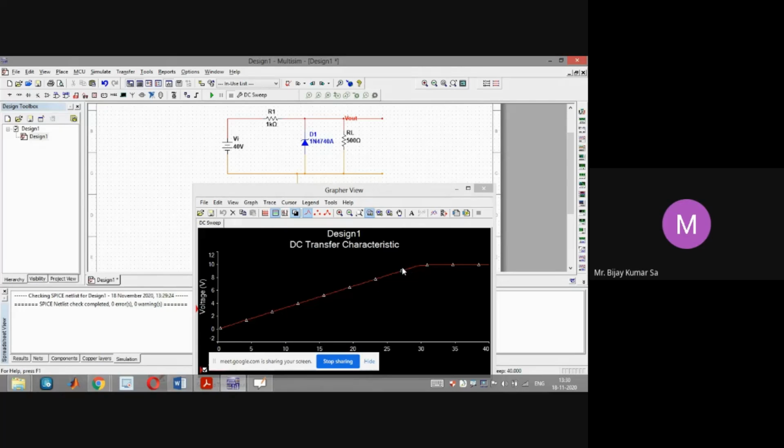Because V output is directly proportional to Vi in that case. From Vi equals 0 to 30 volt, V output is simply equal to VL, and VL is simply what? Vi into RL by R plus RL by voltage divider rule.